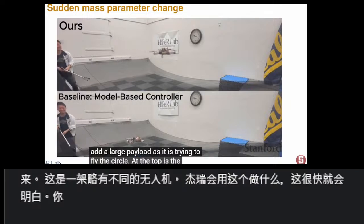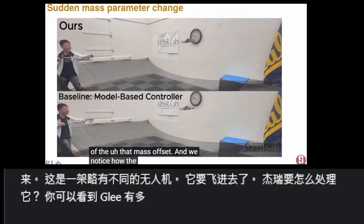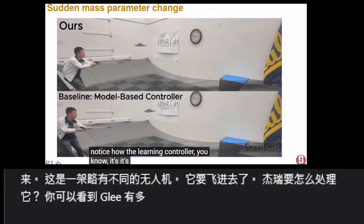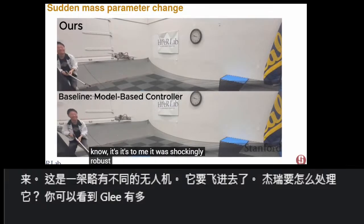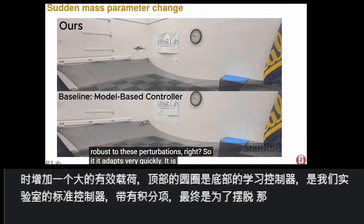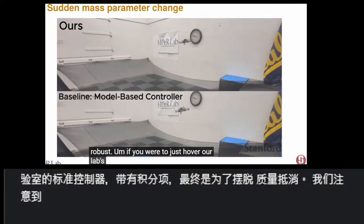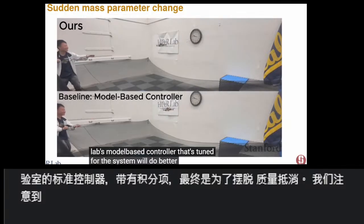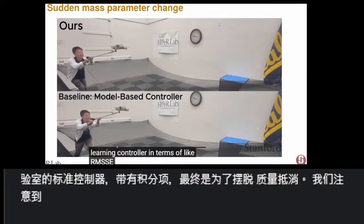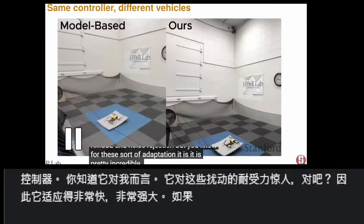At the top is the learning controller. At the bottom is our lab standard controller with an integral term just to eventually get rid of that mass offset. And we notice how the learning controller, to me, was shockingly robust to these perturbations, right? So it adapts very quickly. It is very robust. If you were to just hover, our lab's model-based controller that's tuned for the system will do better than the learning controller in terms of RMSE and noise rejection. But for this sort of adaptation, it is pretty incredible.